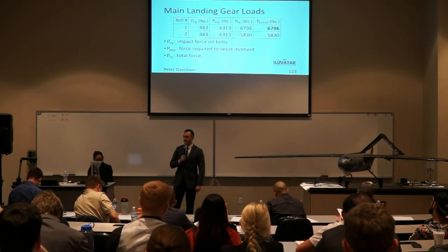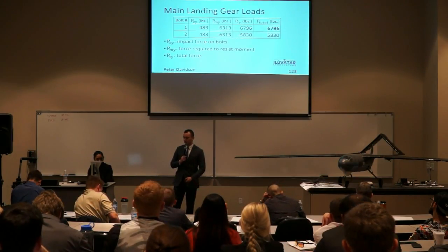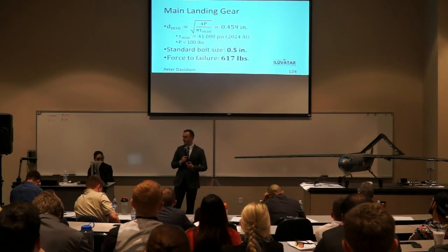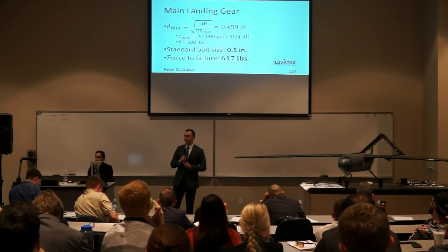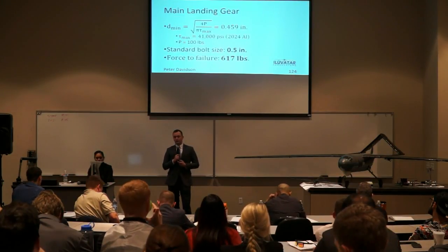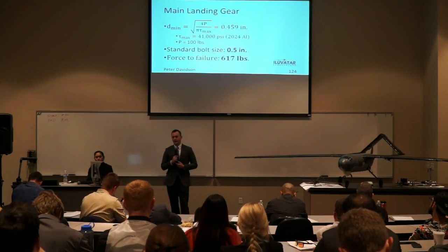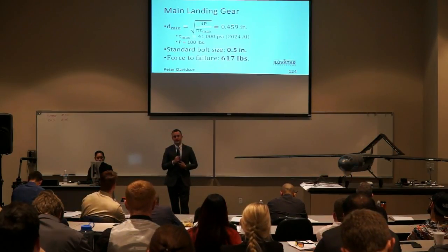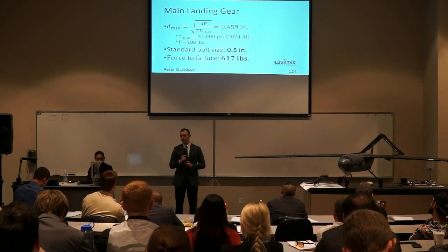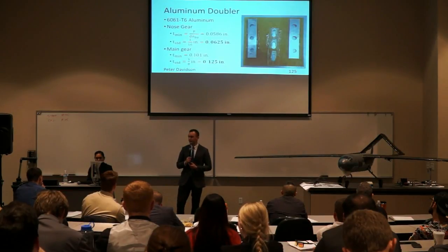So you see 6,796 pounds is calculated as the critical load. For the diameter of the bolt, it's calculated 0.459 inches and correlates to a standard bolt size of 0.5 inches, and reevaluated for that bolt size, the force of failure was 617 pounds.